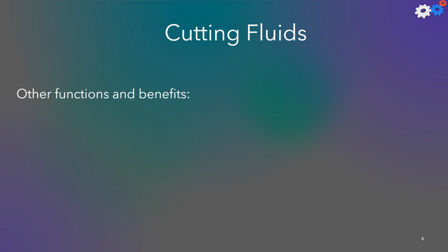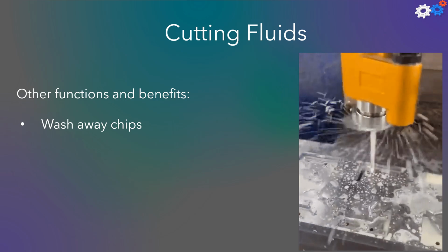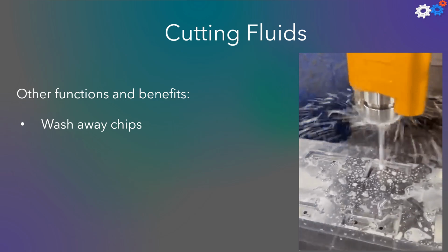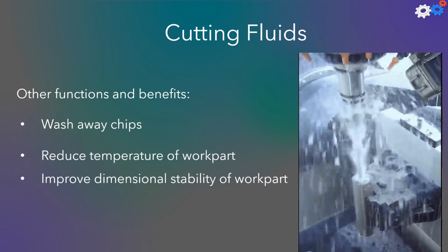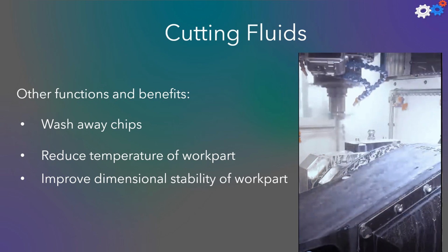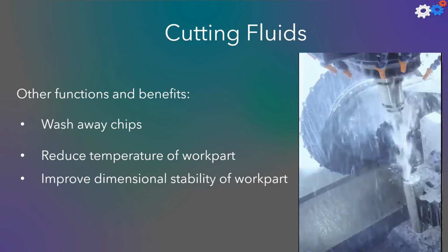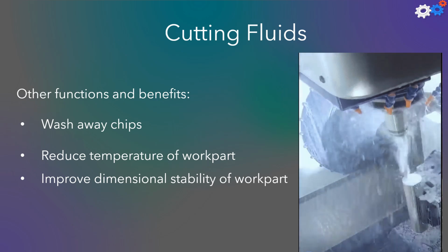Other functions and benefits of the cutting fluids are to wash away chips, for example in the case of grinding and milling, reduce the temperature of the work part for easier handling, and finally improve the dimensional stability of the work part.